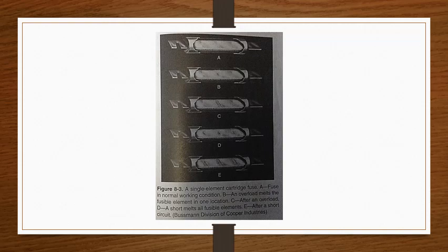within thousandths of a second, less than a half cycle of alternating current, for short circuits and ground faults. Since these fuses act rapidly, they're only used in circuits with no transient surge currents or temporary overloads. See Figure 8-3, which illustrates a fuse melting and opening a circuit.